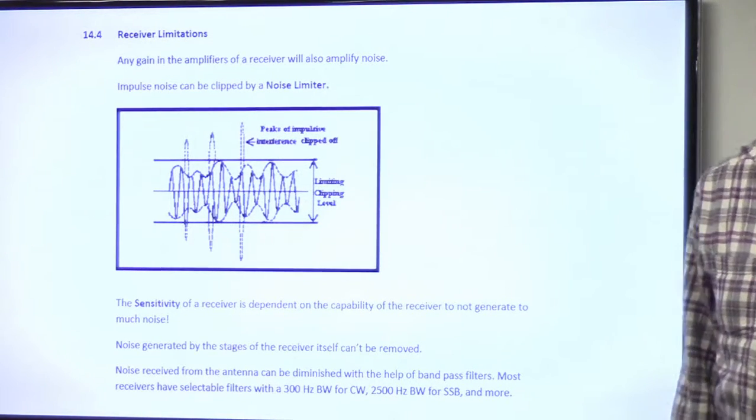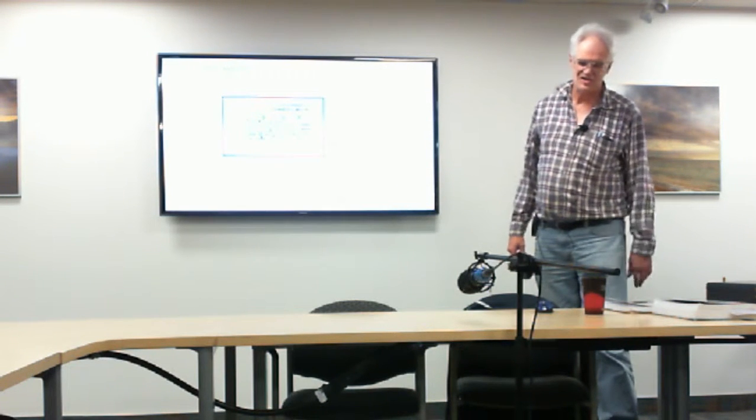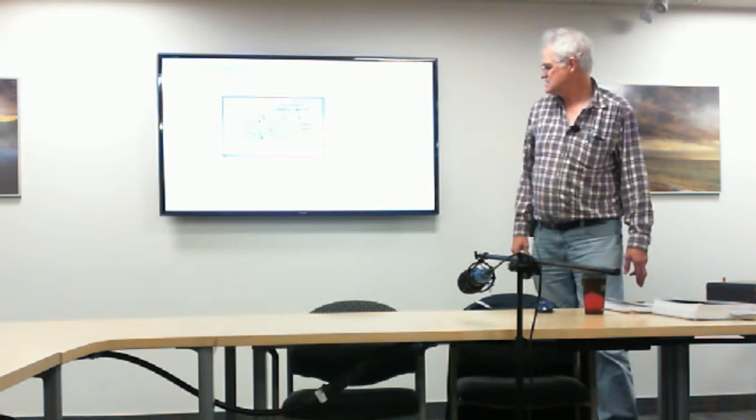And we're going back to, if you remember, capacitors, inductors, tuned circuits, which we use a lot as filters. Because remember, a series tuned circuit will provide the minimum impedance at resonance, whereas a parallel tuned circuit will give you the maximum impedance at resonance.